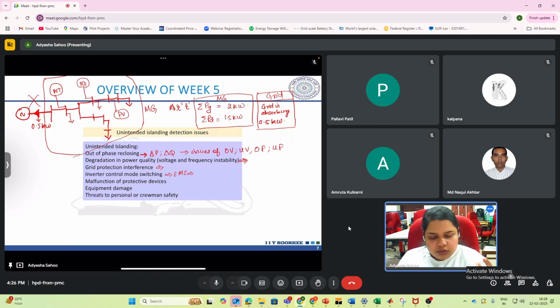To regulate that, it takes feedback from the voltage at the PCC or at the grid, and it is fed into the control loops so that the voltage is regulated. But since now you don't have the correct voltage value, it will again lead to maloperation of the inverters.